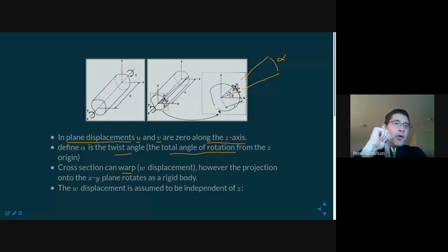On those pipes, because they're exchanging heat and locally cooling the air surrounding them, it brings the relative humidity locally around the pipe to 100%, and then you get condensation and moisture, of course, and that can drive mold. Also, the other argument for insulating your pipes is you don't want to spend energy heating the water that's coming into the house if you just want it to go down the tap as cold water.